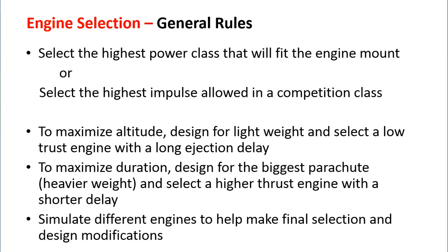Okay, let's see if we can summarize all that and give you some general guidelines you can use in the future. In general, when you go to select an engine for your rocket, you will select the highest power class that will fit the engine mount. In other words, A, B, C, D. You'll pick the highest class that will fit the engine mount, or you'll select it based on the highest impulse allowed in the competition you're entering.